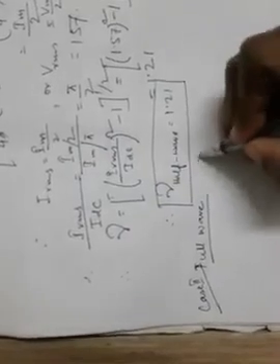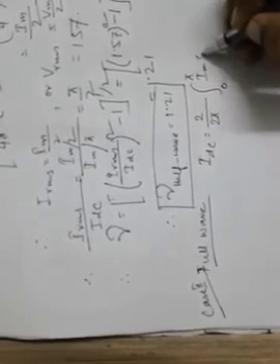For a full wave rectifier, the load current flows in both the half cycles of the input signal, you know already. So IDC in this case is 2 by 2 pi. Why 2? Because 1 by 2 pi is for half wave and 2 by 2 pi is for full wave. It is flowing for the whole of the input signal cycle. That's why this 2 is taken, and the rest of the expression is the same as it was for half wave rectifier.